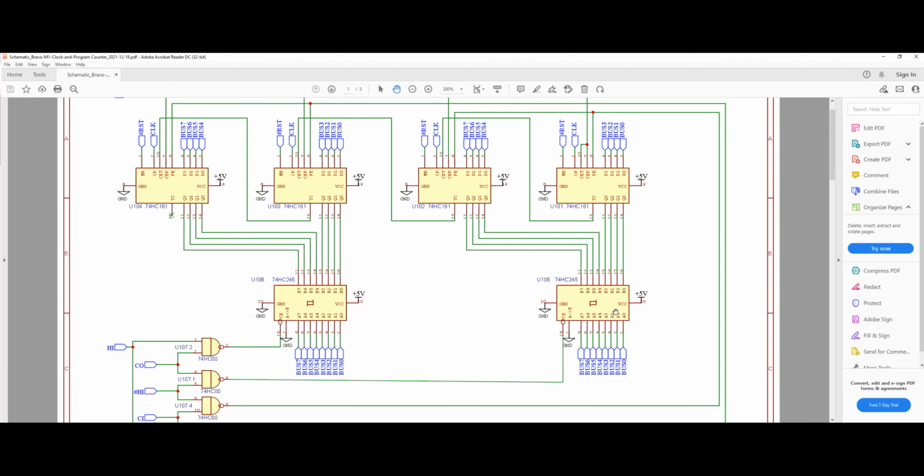In this circuit, the direction is always from B to A, and that's why we set that pin low. Other than that, we only have a single pin here, which is chip enable, pin number 19. It's an active low pin, so when you bring it low, it puts the data on our output, or on our bus here. So that's really all about the transceiver.